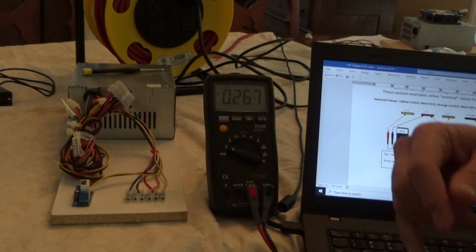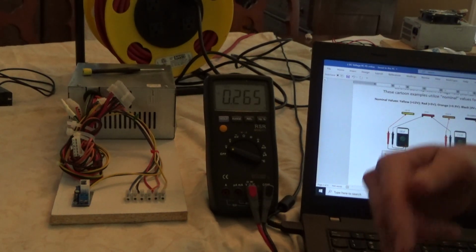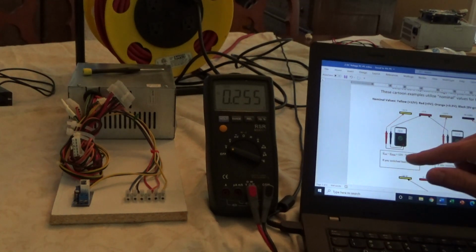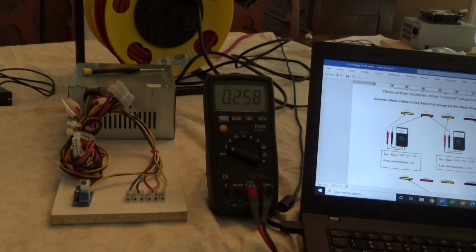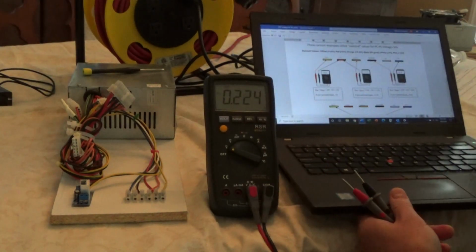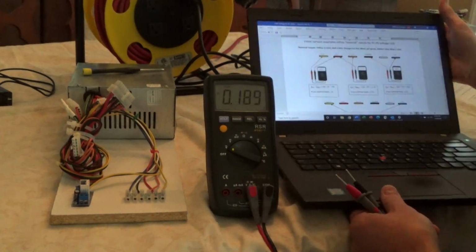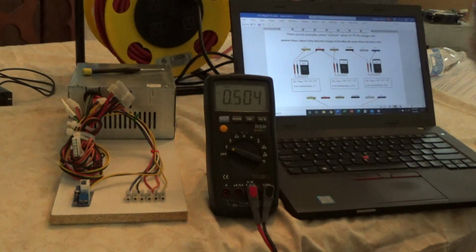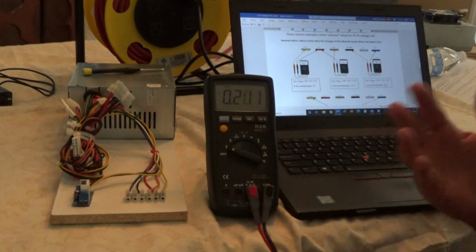Because what you're doing is measuring a voltage drop, a change in voltage. So that would be 12 minus 5 is 7, so a plus 7 volt difference. And what's interesting about that, in your first semester physics, you might have been exposed to the idea that there's really no such thing as zero potential energy. You just define it somewhere to be zero that's convenient to solve the problem. Basically you can only measure changes in potential. So in electronics, that's like a voltage drop.